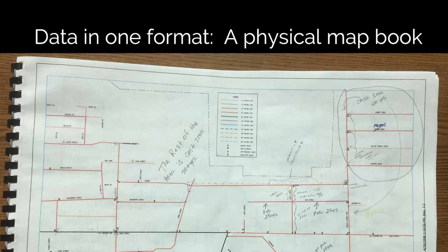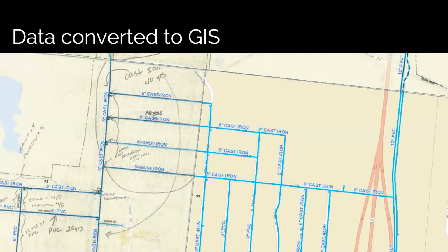So the takeaway here is, regardless of what sort of mapping system you're using, whether it's paper or digital GIS, it's a really good practice to periodically consolidate updates and new information and look for those inconsistencies, so that your maps remain uniform and up to date. Just like the inventory, the more up to date it is, the more useful it's going to be. If you have paper maps and you're interested in moving into a digital GIS system, those paper maps are an incredibly useful source of information for getting started and can be incorporated directly into the digital GIS. This is quite often the starting point that we use for mapping projects.